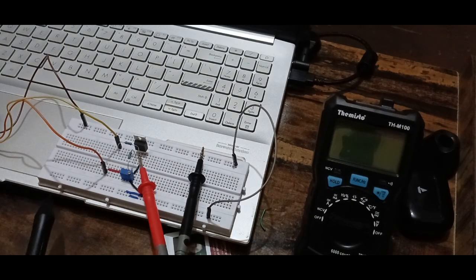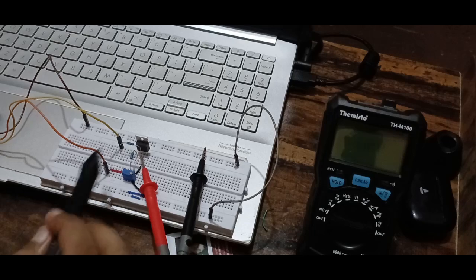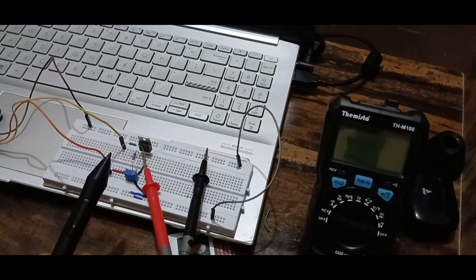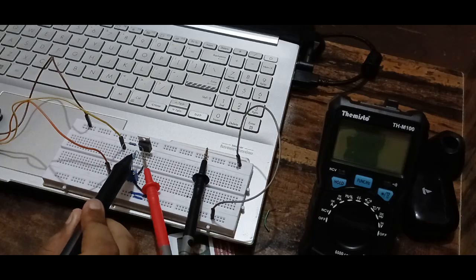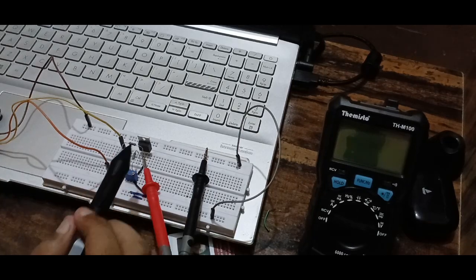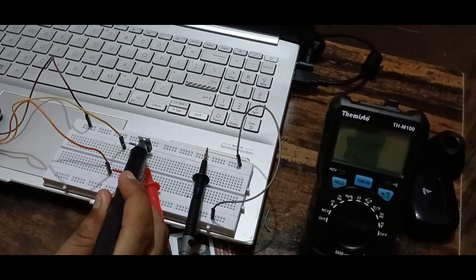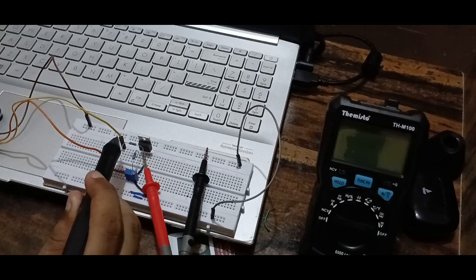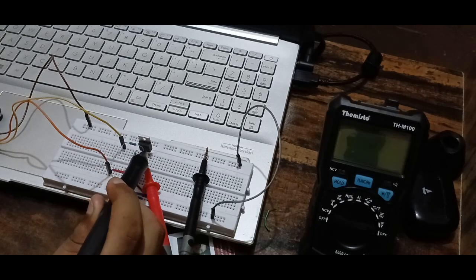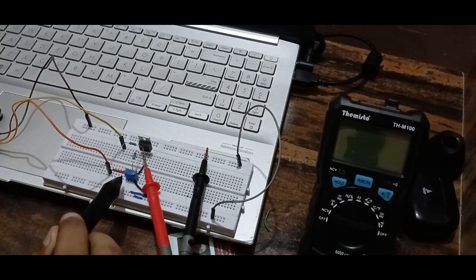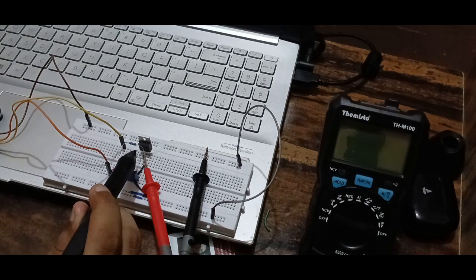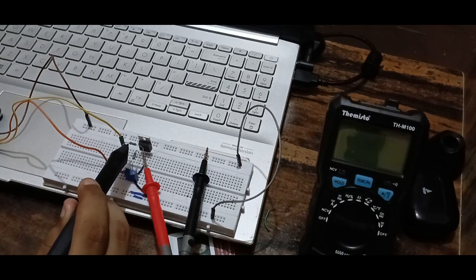So now in part 1 we were asked to replace the BJT with this MOS. So now I'm going to break down the pin connections. First pin is our gate, second pin our drain, and third is source. So this VCC feeds to the drain, and the output of this pot is connected to the gate, and the resistance is 1 kilo ohm.